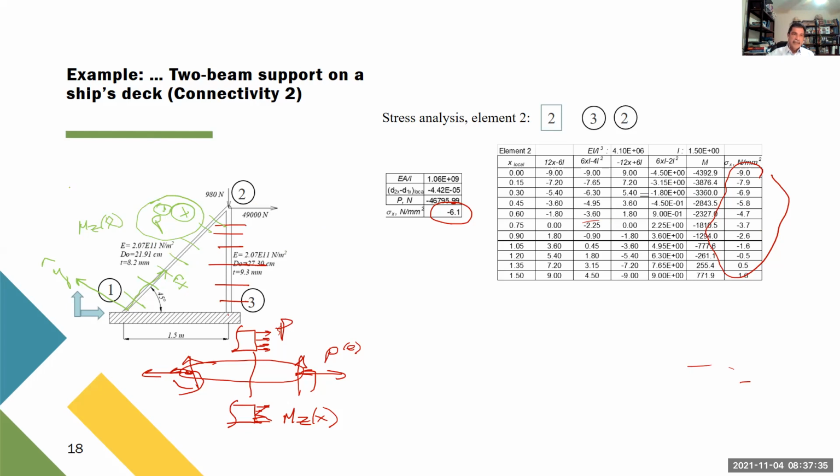So in this case, let's suppose that we have something like this, okay? We have tension because this force is positive, but also you have to combine with the moment. So probably you're going to have something like this, tension here. So you see that on this side of the section, you have positive stress. And also here you have positive stress.